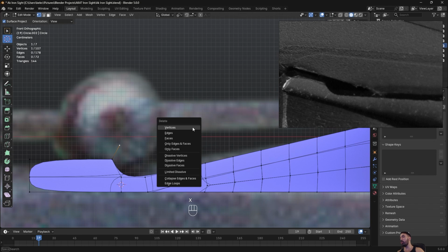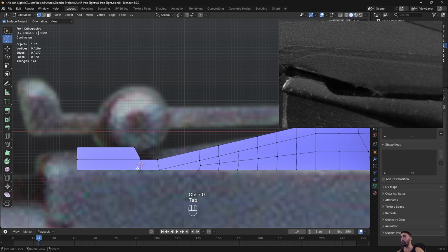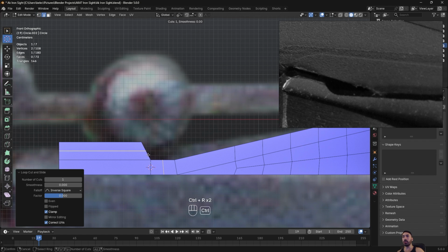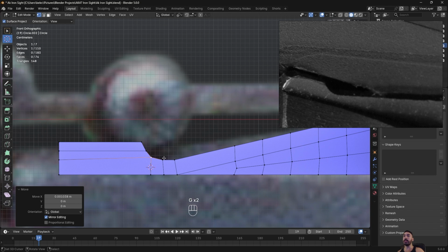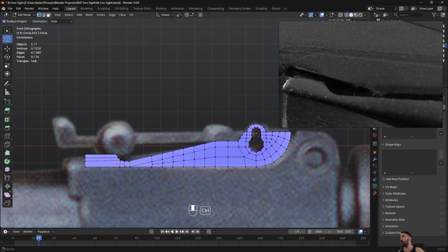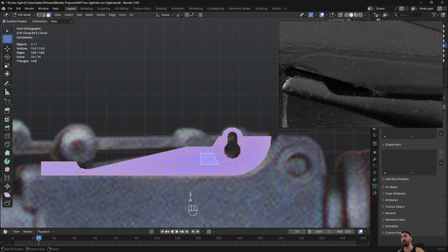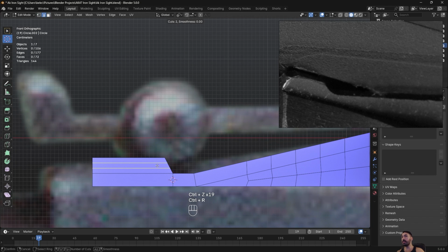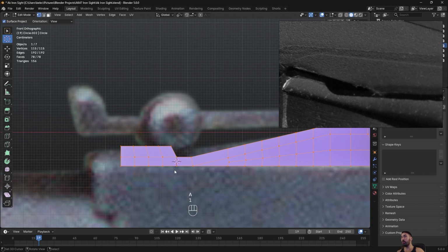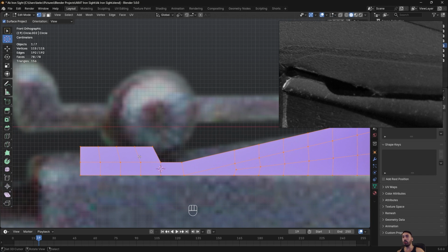Of course, if you don't want to use a subdivision surface modifier, you're not going to do it like this. Instead, you're probably just going to have a little bit more geometry here to get that shape like this. In fact, if you're not using a subdivision surface modifier, then you might as well just turn this entire thing into an ngon, and in that case this tutorial is a complete waste of your time. But since I'm a gentleman, I do care about my topology, so I am going to maintain some geometric consistency,